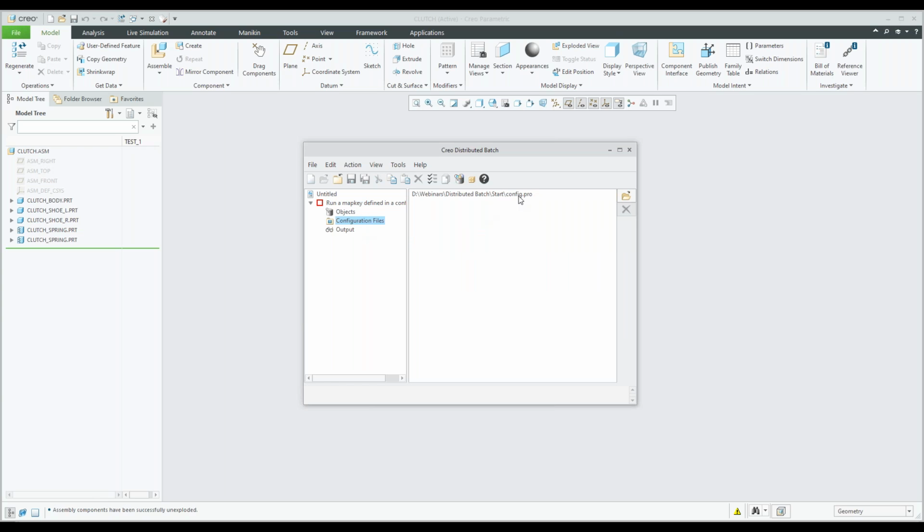And then in the config.pro that we've selected, the map key sequence is saved in there. So we need this config.pro file with the actual steps of the map key. Your TDD file will just go and look at the config.pro file, grab the map key that you've specified, open up the parts, apply the map key, and then save it again. Good.